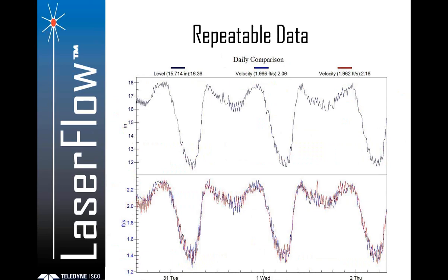The other thing that we've done a lot of testing with is just repeatability of the data, installing laser flows side by side or in tandem on a stream, one facing upstream and one facing downstream, and looking at the flow rate right here, how nicely they tracked right along with each other.